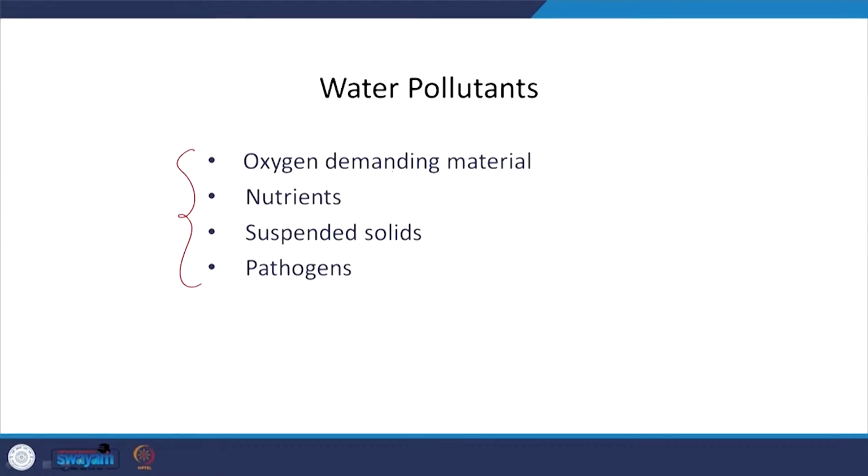In the context of organics, we try to understand or measure them in terms of oxygen demanding materials. So, biochemical oxygen demand, typically over a 5-day period, and the chemical test, COD, chemical oxygen demand, typically takes 2 to 3 hours, right, including setup time it takes 3 hours.